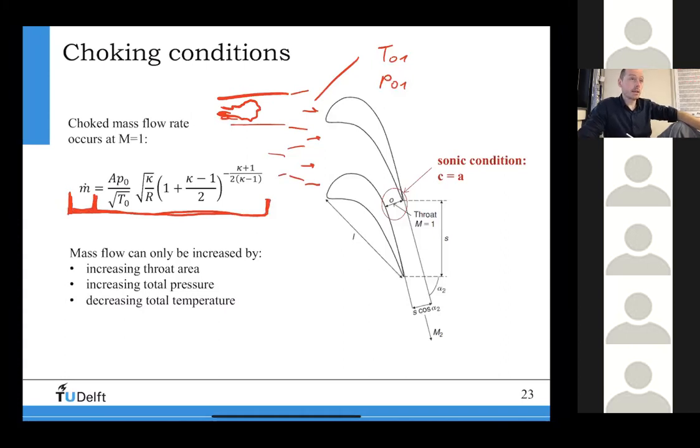And as you can see on this equation, let's say if kappa is always the same, because you're only dealing with air, for example, then this whole part will be just a number, right? Because what is in there is kappa or gamma, which is 1.4, let's say, for air, and R, which is 287 joule per kilogram and Kelvin. And then you will see that this is just a constant, right?